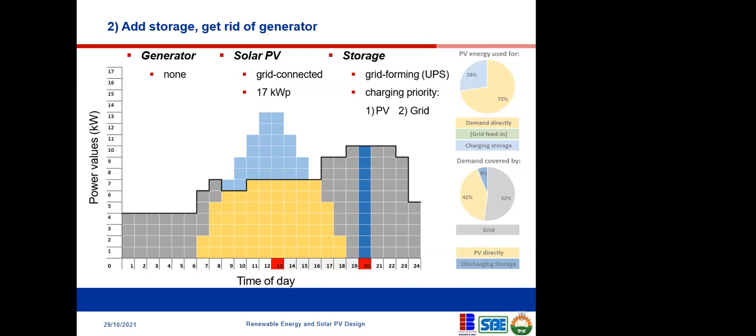So for you to reduce those excessive costs, it's advised that you do a hybrid system where, instead of having oversized solar systems, you can combine it with your generator and then you optimize the entire system. Now your generator is scalable. Understand? It's scalable in the sense that it can move along the path of your load demand, right? If it's meeting a higher demand, then it's burning more fuel. If it's meeting a lesser demand, it's burning lesser fuel.